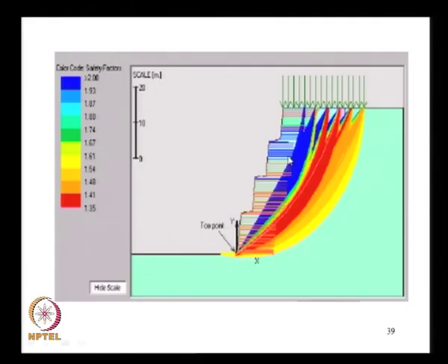And here you see the result from the slope stability software that indicates the different types of safety factors that were obtained. The blue color indicates that the factor of safety is greater than 2, and this red color there is a patch that is actually very close to our active rupture surface. It has a factor of safety of about 1.35, and this yellow color has a factor of safety of 1.6, and this 1.35 is after including the seismic factors in the analysis.